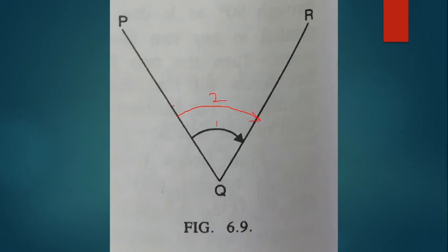So here again I need to release the upper clamp and turn the telescope towards R and Q. Now approximately bisect R with the help of the clamp screw, and fix the upper clamp, and with the help of the upper tangent screw you can exactly bisect the ranging rod on R. Now with this we have completed the second repetition, and the instrument is ready for taking readings at the second setup.